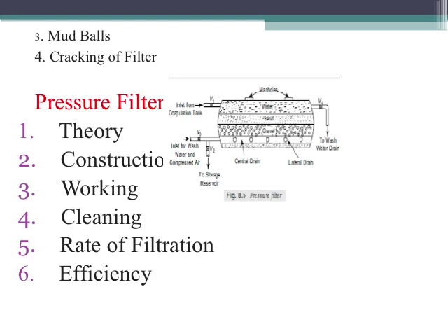These mud balls slowly go on increasing in size and weight, and they start sinking down into the gravel, which will in turn interfere with the upward movement of the wash water during the backwashing. They even cause turbulence around them and hinder the uniform application of the wash water, because we know that uniform distribution matters much during the backwashing process.